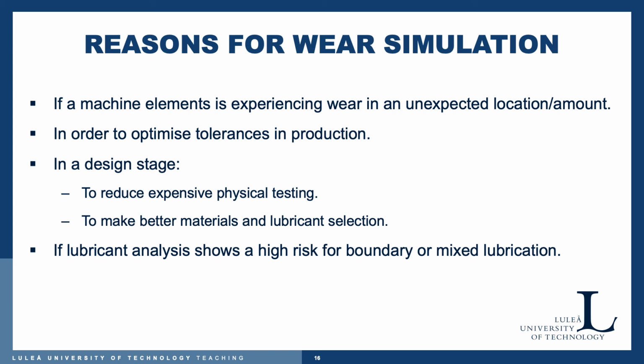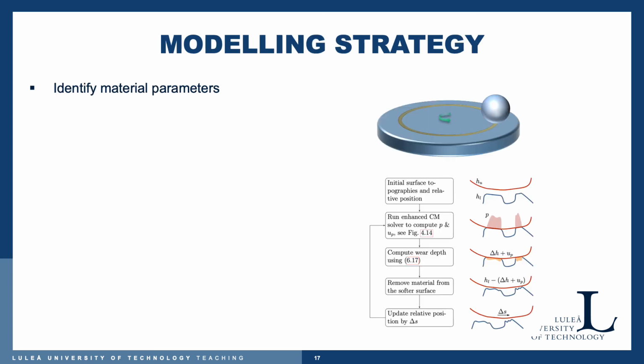We can also run wear simulation if there is a high risk of boundary or mixed lubrication, because then we know the surfaces will wear, and we can definitely be helped by understanding a little bit more about how much it will wear and so on.